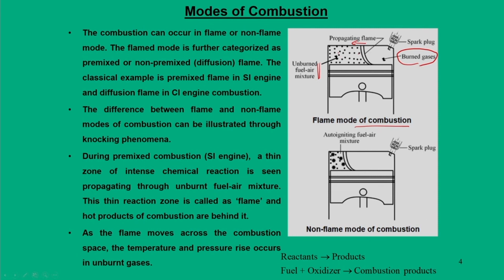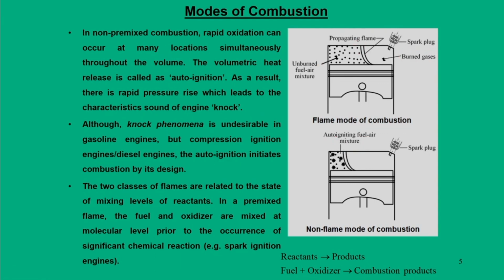Similarly, in a CI engine, when the flame moves, there are regions where auto ignition takes place for the fuel and air mixtures. That is mainly because the fuel and air are considered as separate entities, and they come and mix locally at one particular position in the engine cylinder. So, that is the basic difference.